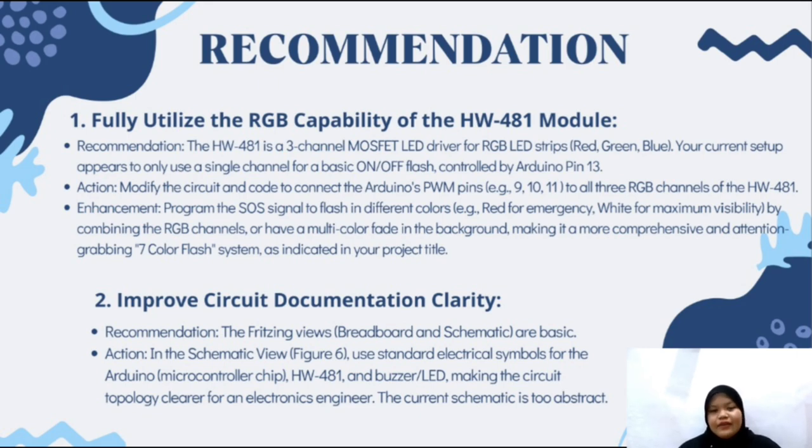Next, we can improve circuit documentation clarity. For the recommendation, the Fritzing views, which are the breadboard and schematic, are basic. In the schematic view, in figure 6, we can use standard electrical symbols for the Arduino, which is a microcontroller chip, the HW481, and the buzzer or LED, making the circuit topology clear for electronic engineers.